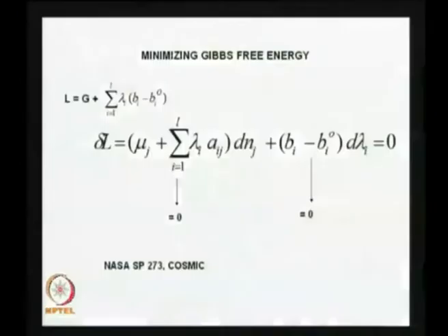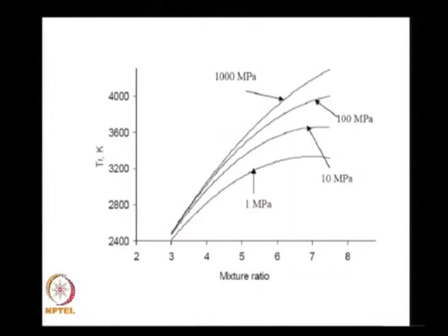I did present this earlier. Now, having understood the problem, let's see how the flame temperature changes with mixture ratio for a hydrogen oxygen reaction. Mixture ratio 8 is stoichiometric, and as I said, we always operate in the fuel rich region. At higher pressure I find a higher value of temperature than at lower pressure. Why is it?